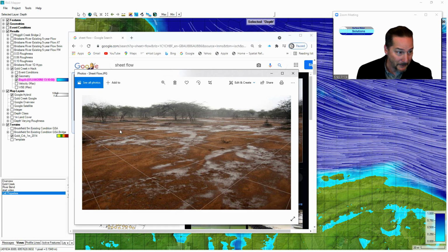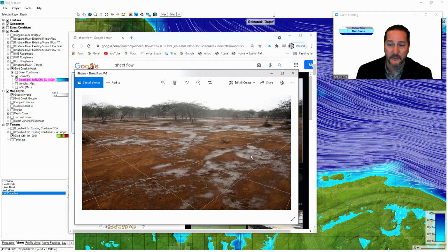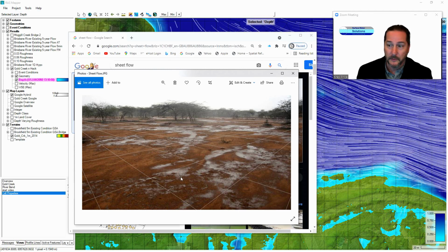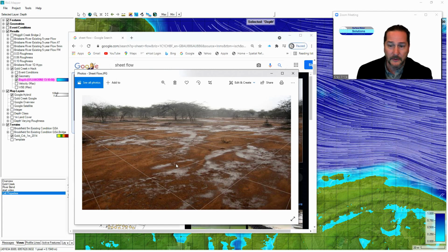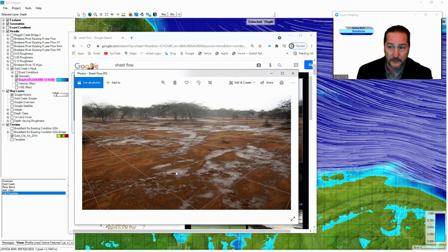Well, and then picture what happens if you put vegetation on this, or if you make this steeper. If this sprouted into a field or into a paddock where it's all filled with grass, of course, the ground and then any vegetation on it would look a lot rougher to the shallow flows like this than it would to deeper flows.